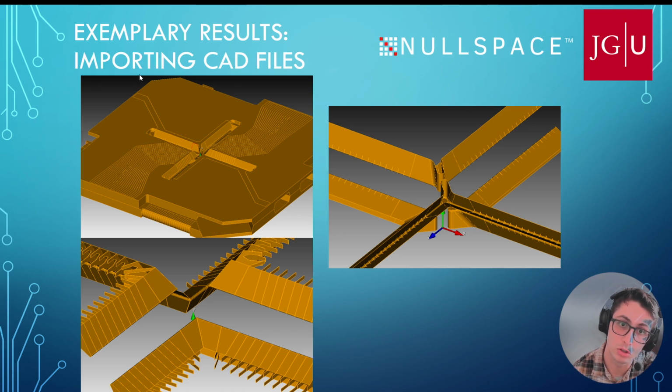Well, this is the SolidWorks CAD file that we use for 3D laser etching. That's how we made these traps, the production process. And we import the same file. Maybe sometimes we have to adjust some dimension, but we import the same file, and then we defeature unnecessary geometry features, and we select the relevant surfaces.